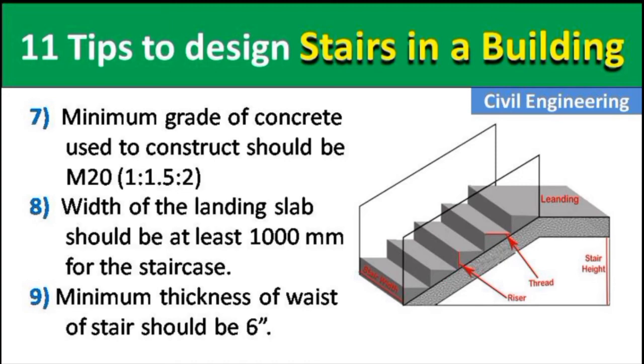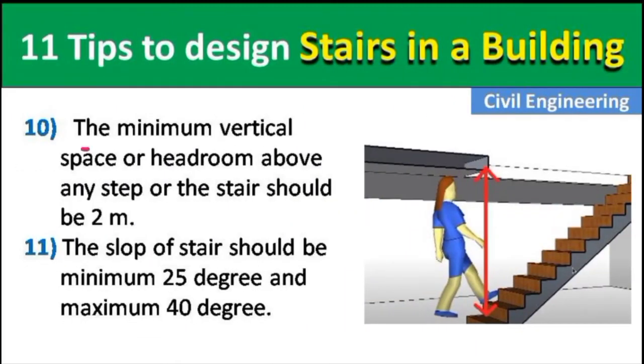Okay, now point number 10 is the minimum vertical space or headroom above any step or stair should be 2 meter. You can see in this picture, from here to here, this is known as headroom. Okay, so this should not be less than 2 meter, because it may hit the head of this man, who may collide with the slab. Okay, so we should provide how much? 2 meter as headroom.